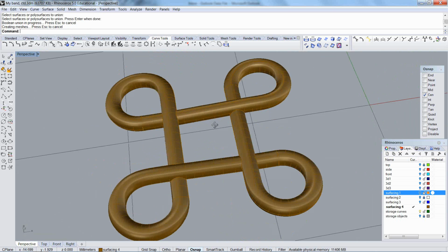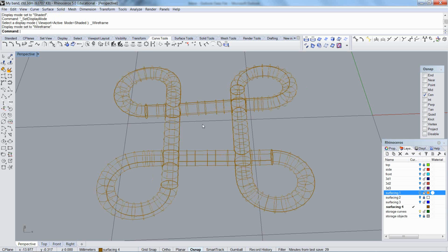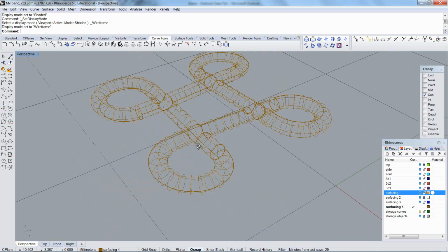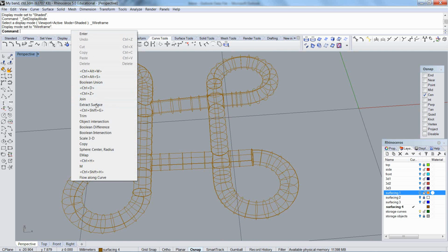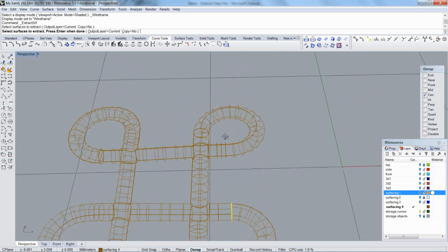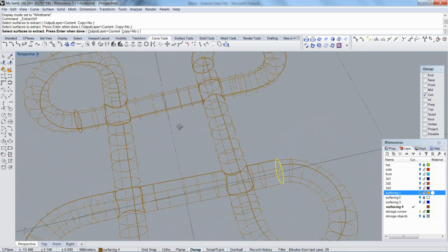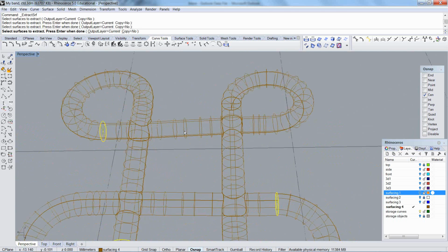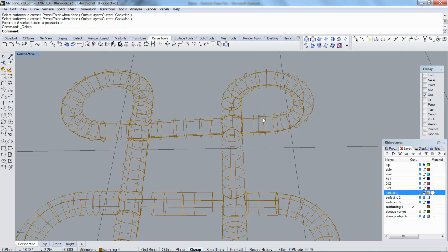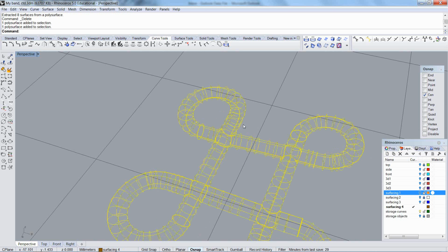See how helpful Rhino is? It made me a Boolean object. Everything's perfect. Except for, no more self-intersecting geometry, but I've got plugs everywhere. So I'm going to remove those. Anywhere I see them, drag a window around them, as long as I'm in the extract surface command. And delete them. Now the problem is Rhino doesn't show anything wrong with this unless I turn on naked edges.